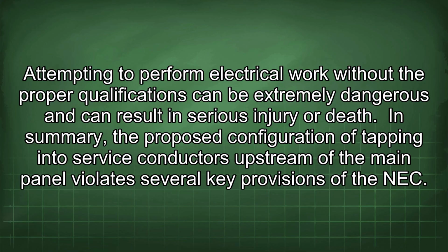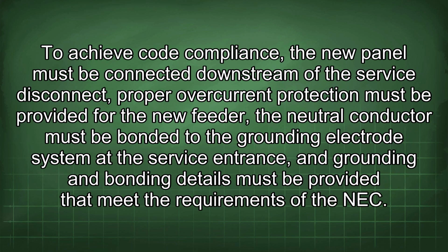In summary, the proposed configuration of tapping into service conductors upstream of the main panel violates several key provisions of the NEC. To achieve code compliance, the new panel must be connected downstream of the service disconnect. Proper overcurrent protection must be provided for the new feeder.